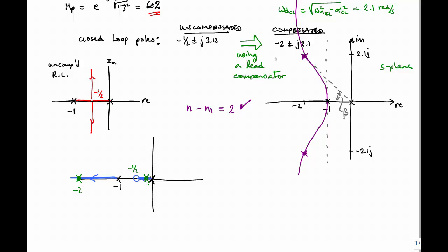Well, now, what pole is the dominant pole in my system? The dominant pole in your system is always the one, or the ones if it's complex conjugate, that are closest to the j omega axis. So this system is going to have a dominant pole that is close. That's actually worse than our system originally, right? Our original system had a real part of -1/2. Now this dominant pole is to the right of -1/2. So that's clearly not helpful.